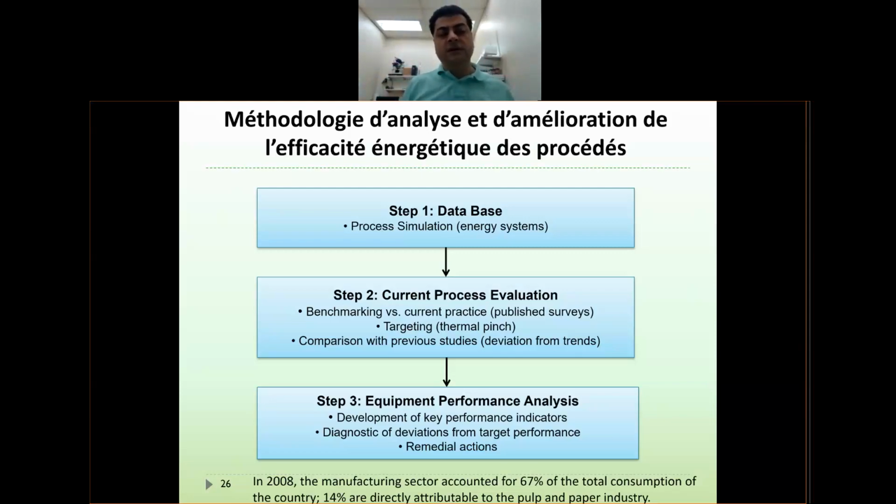In other words, when you simulate and then apply an improvement, you always assume the equipment is going to work perfectly. But as a matter of fact, the valve, for example, undergoes aging, is old, doesn't seal when you close it, so it doesn't perform very well.